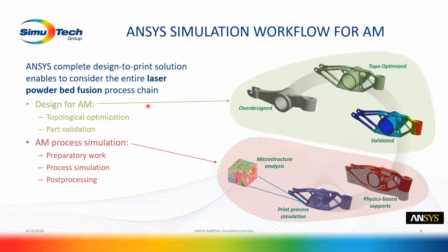It starts with the part that is called design for additive manufacturing, which basically focuses on topology optimization, and then goes into the additive manufacturing process simulation to, for example, select the proper orientation, generate some physics-based supports, simulate the process itself, and then predict some outputs in terms of microstructure, mechanical properties, and all of those different things. So this is where ANSYS is in terms of additive manufacturing: a complete design-to-print solution.